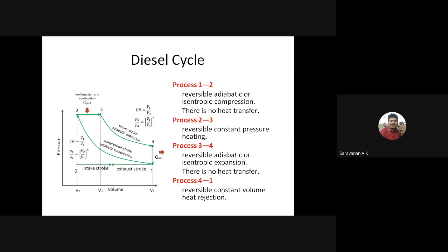Then the diesel cycle. Compared to the Otto cycle, the only difference is the heat addition, which is at constant pressure. Everything else is the same as the Otto cycle. Here we can add one more thing: the cutoff ratio.